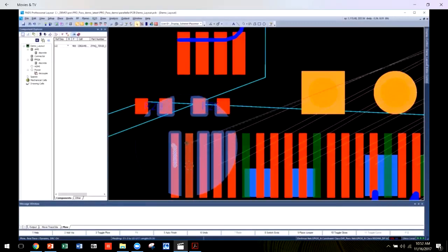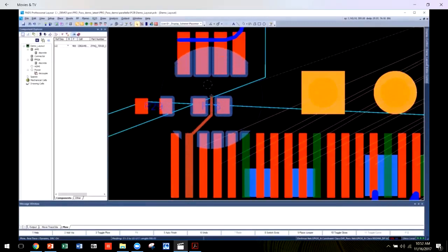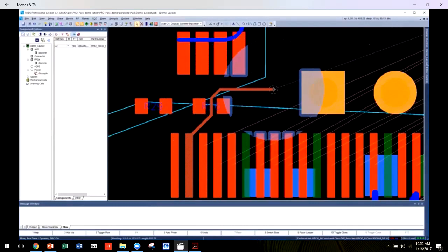One of my favorite features to use when routing is the active clearance dialog. The active clearance bubble shows a blue shadow of the actual clearances around your cursor while interactively routing in real time. The clearance keepouts are easy to see while still providing enough transparency to not be distracting. Active clearance provides quick visual feedback of available routing paths. It is also extremely helpful in identifying the clearances of objects that will prevent a trace from entering a tight space. Active clearance will reduce your frustration level in highly dense areas when traces just won't go through.